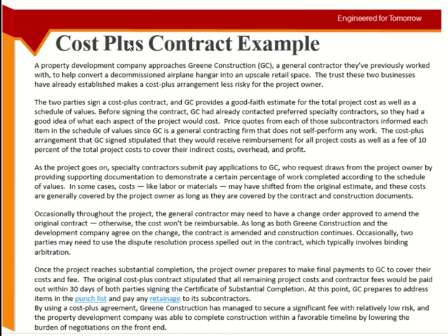What else? Yeah, the change orders are allowed. The contractor can give the change order. The point is, before carrying out the work, the change order must be approved. If he does something without approval, then the cost will not be given. Otherwise, whatever new changes are approved, the contractor can bill for it. Clear? What else?